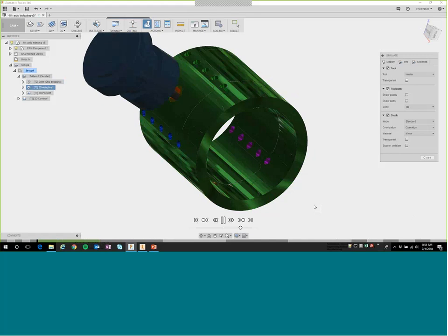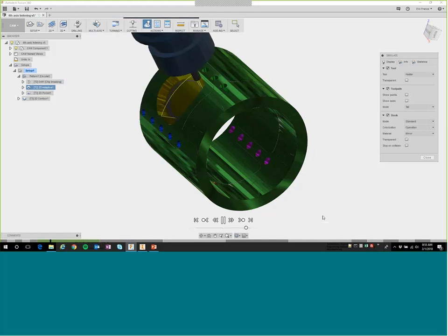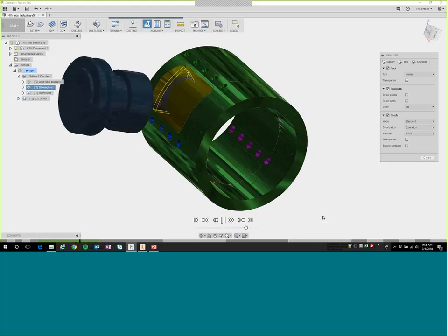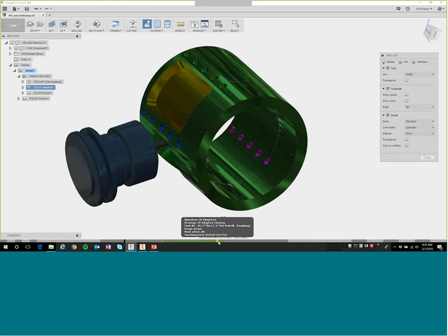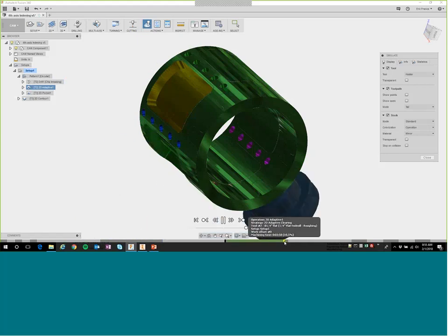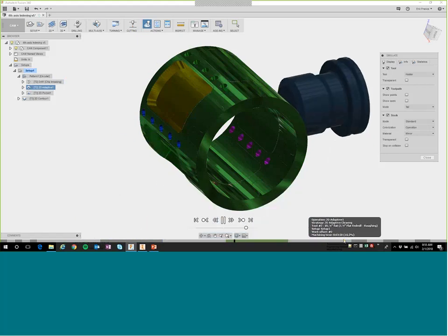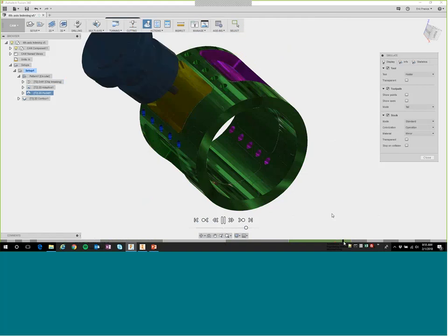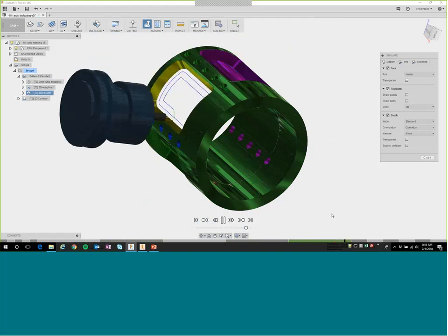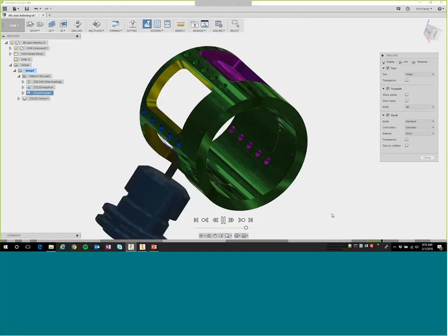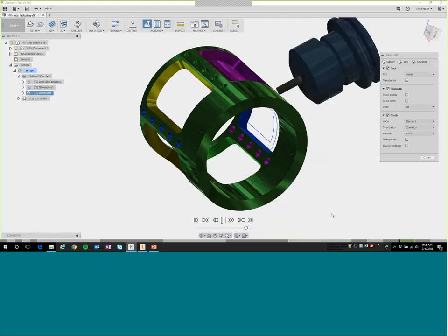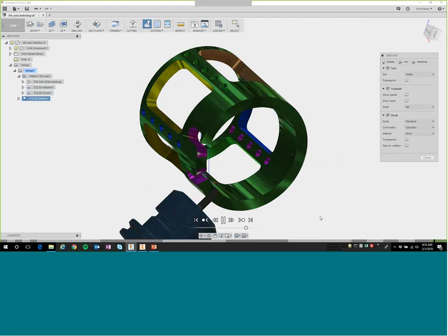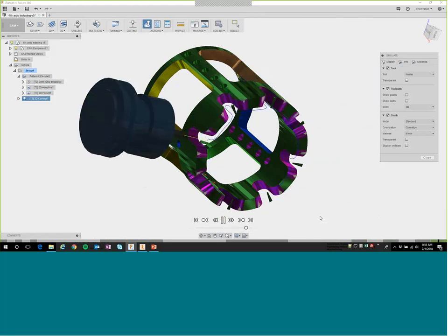And now it's going in, and we're going to speed this up a bit more to move through the rest of this geometry. But it's going in and doing those milling operations or the clearing operations, which really don't show us a whole lot. But now we can see it there. It's clearing out all that material, actually breaking through. The nice thing about doing that roughing operation, leaving some material and then coming back in, and there it's going in and doing the contour.